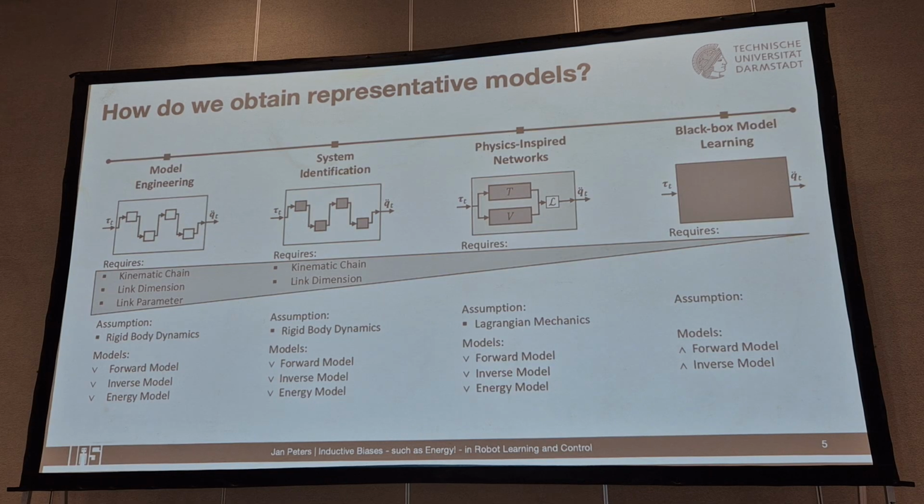Here you have basically the taxonomy of models. On the very left you see what we did before: system identification, take the robot apart, measure everything, and we get everything beautifully consistent with physics, with only the problem that there are things like friction, like actuator dynamics, and when things bend and are impossible to measure, we get a really, really big problem.